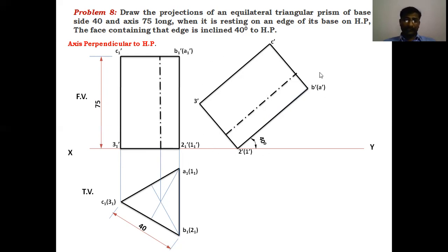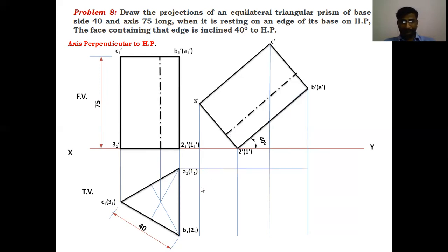After getting these points in the front view, draw the projection lines from each point. This is the upper base points projectors. Similarly, draw the projectors from the bottom base points. Those are the vertical projections, and draw the horizontal projections from this diagram, the horizontal projections from 3 corners. Then first draw the upper base, locating the upper base points, that is the lettering points.